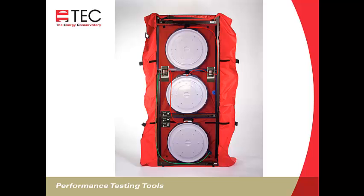Because we've got three fans here, when these are all running, we're going to have a lot of turbulence in this area. So we've got 4 open taps now. The 3 reference pressures and the input for the envelope pressure are all open taps, and they'll see a lot of turbulence and airflow in that space. So we want to connect tubes to those and get them out of the turbulence of the fan.